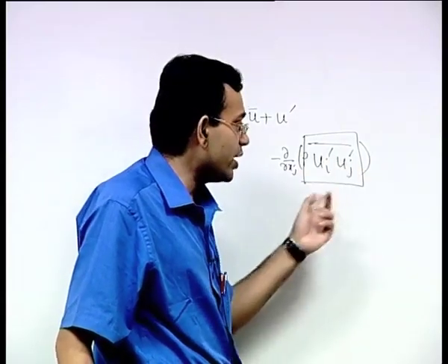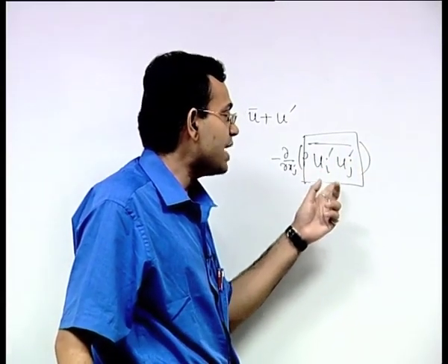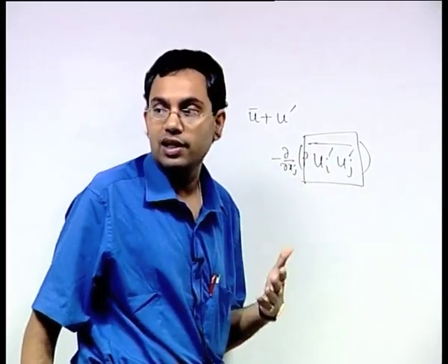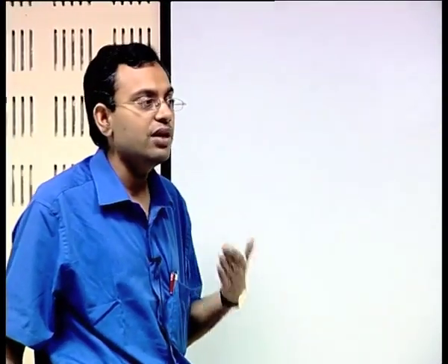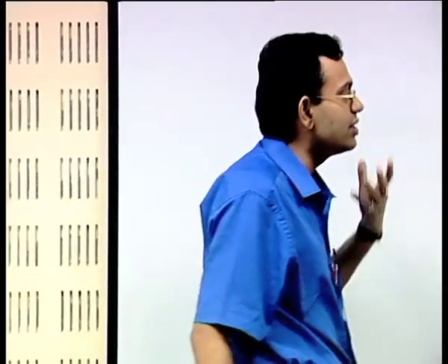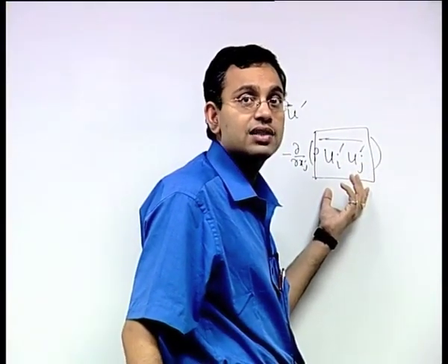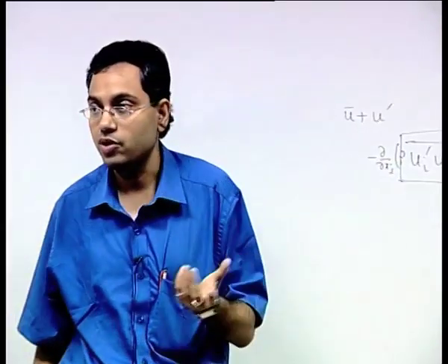So these new unknowns do not have matching number of governing equations and they need to be closed by suitable modeling. So you do not have matching number of equations with unknowns when you come up with the Reynolds average Navier-Stokes equation, and you need to close this extra number of unknowns by appropriate modeling effort, and that is known as a closure problem in turbulence modeling.